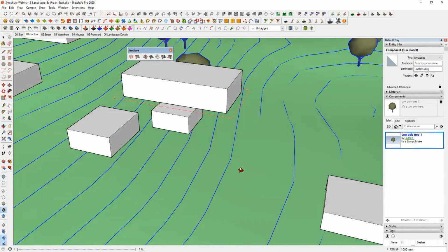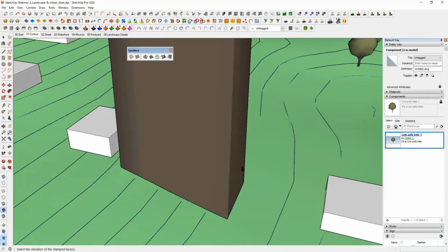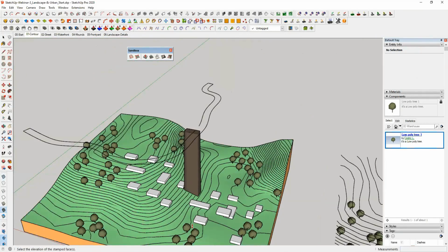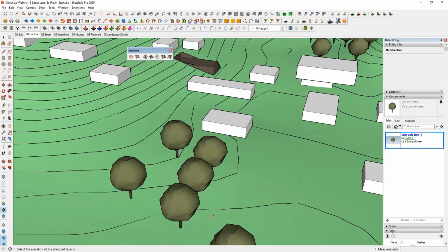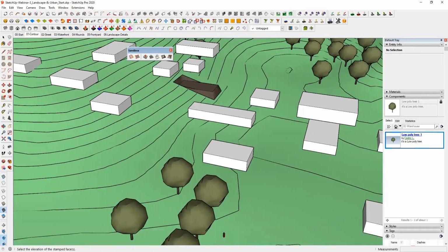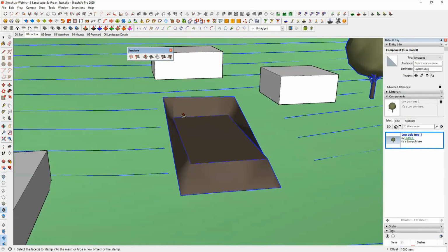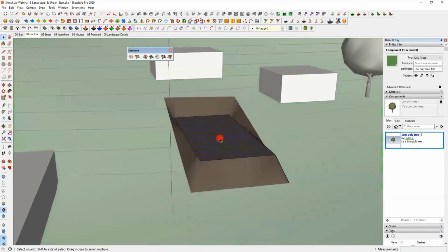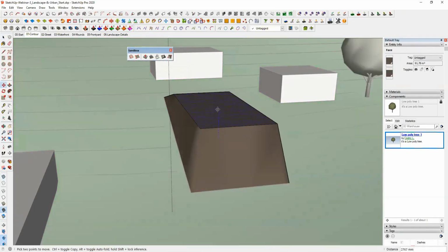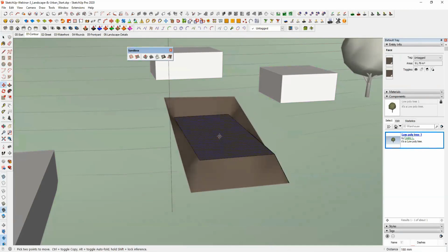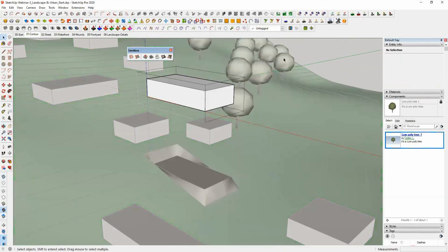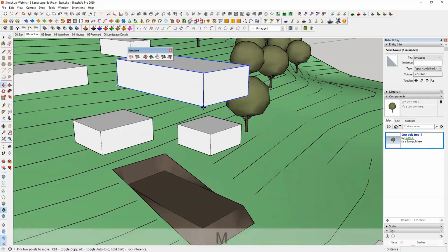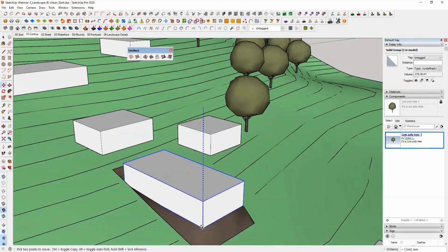So let's click on the terrain. Now again, it is going to create an elevated object. I mean, it is going to create a flat surface now, and we are going to place it so that we have the appropriate cut and fill. And even once it is fixed, you can go ahead and move the level up and down so that you get the right level. And after that, we can move the object and place it on the terrain.